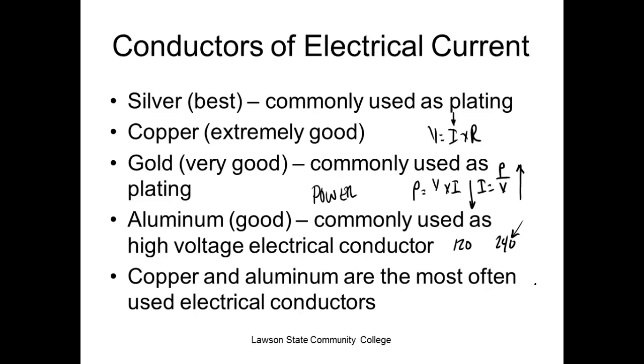It's just that the lower the voltage I deliver that power, the higher the current has to be to deliver that power. I've got to run that through conductors. Conductors have resistance. What determines the resistance of a conductor? The size. So Alabama Power is trying to send me 750,000 watts, and they're doing it at 120 volts. What size would the conductors be? They'd be as big as buses, just to get that there.